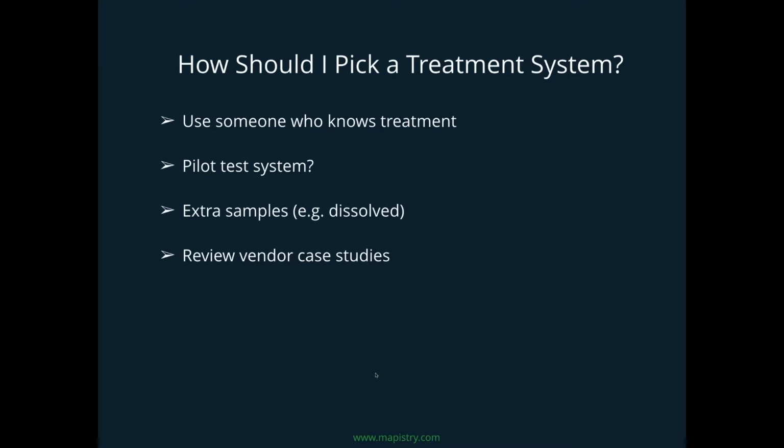If you can't go to one of those lists, how should I pick a treatment system? Use someone who knows treatment systems, a professional engineer that has specific experience in stormwater and stormwater treatment, or other practitioner that has done specifically stormwater treatment. You might want to consider doing a pilot test before investing in a large system. Have a smaller scale system that tests a side stream, so you can make sure that approach is going to meet your effluent concentrations.